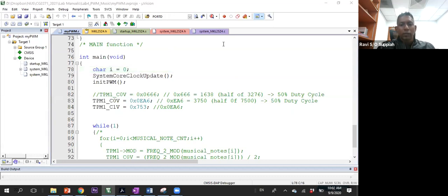We need to use two channels because, at the bare minimum, you need to control the right side and the left side of the robot. So one channel for the right side, the other channel for the left side. Whether you want to split it to both right motors and both left motors is something that you can decide how you want to do.